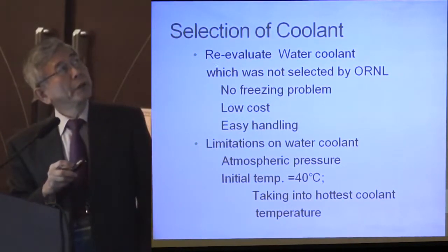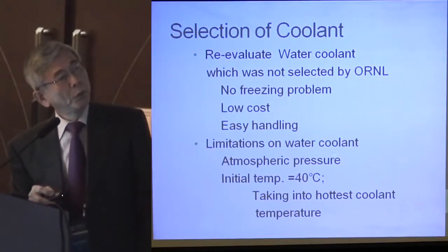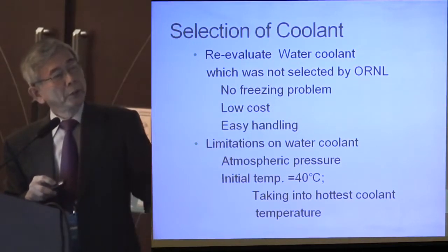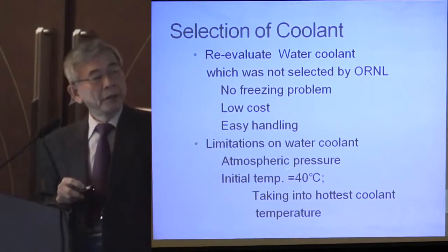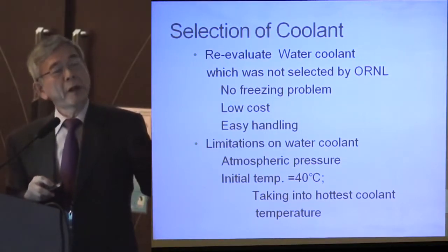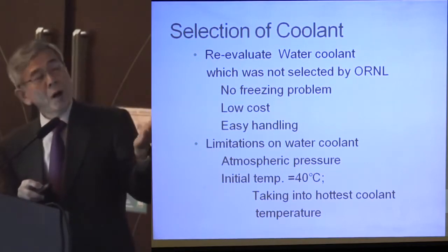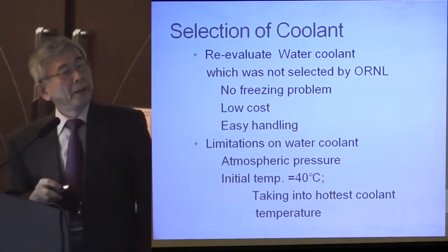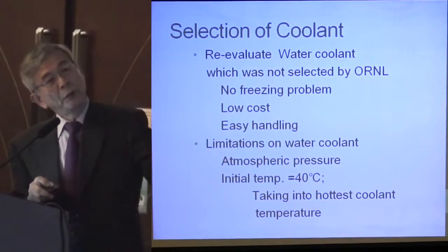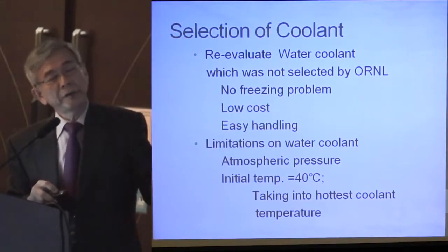And as we select the water, we set the limitation of water coolant: the temperature should not go above the boiling point. That means 100 degrees Celsius. And the initial temperature of the coolant, we assume 40 degrees Celsius.